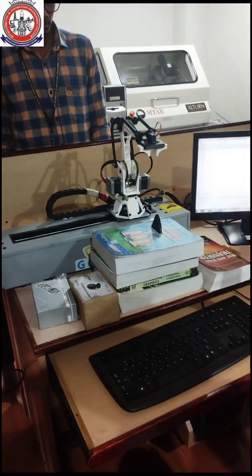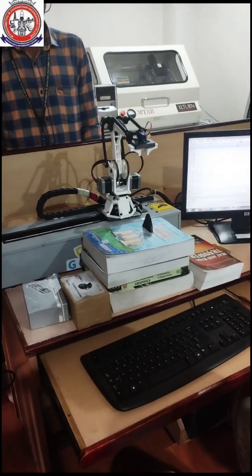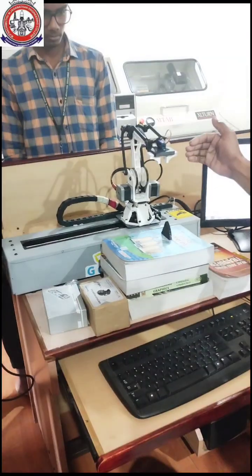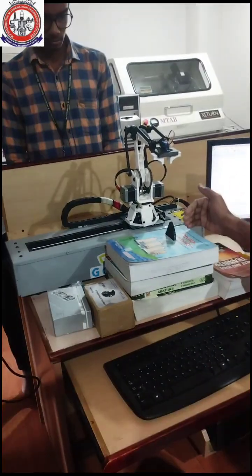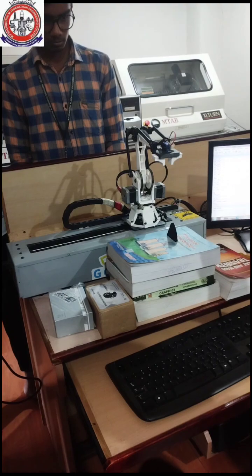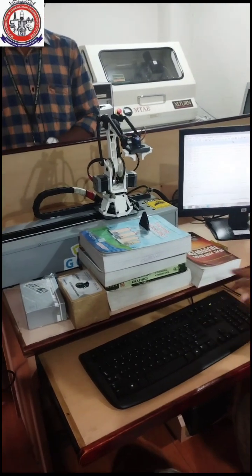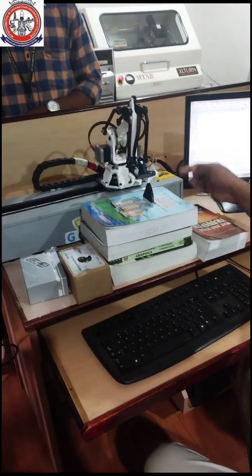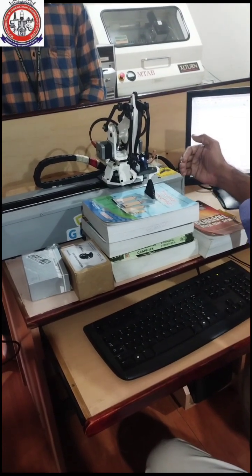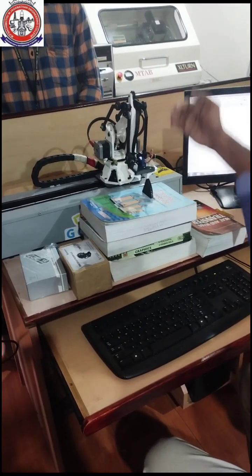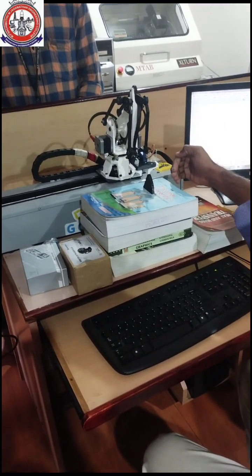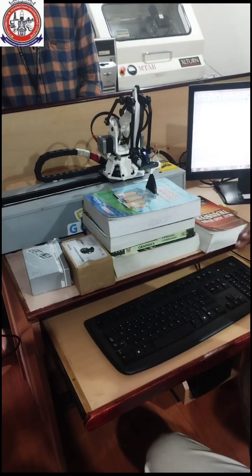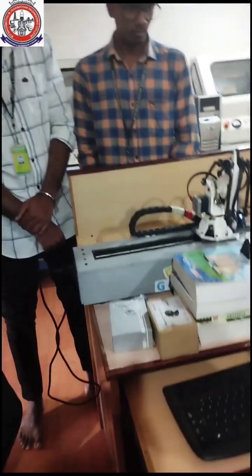If you give Z axis minus 60, the value will go down based on our graph. Minus 60 means the gripper will go down like this. Then you press enter, and it goes down for the Z axis position only. If you only give the Z axis position, the gripper will come from top to bottom by minus 60. Now what code do you give so that this object is picked, and which axis will change?